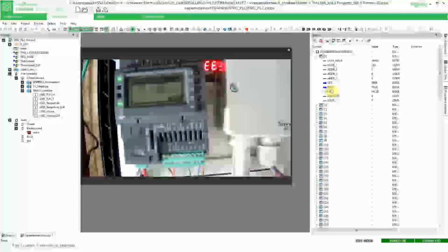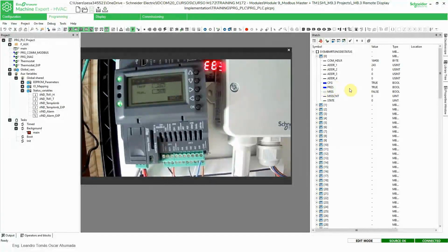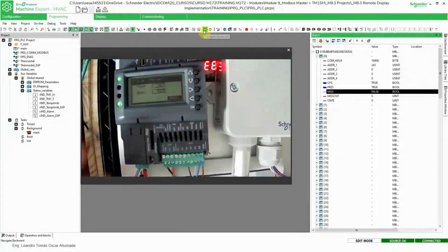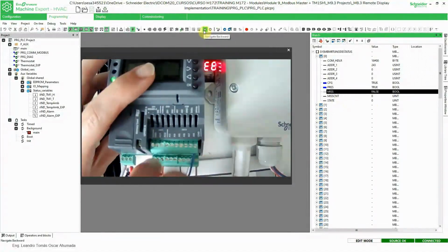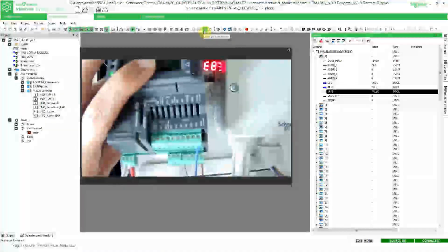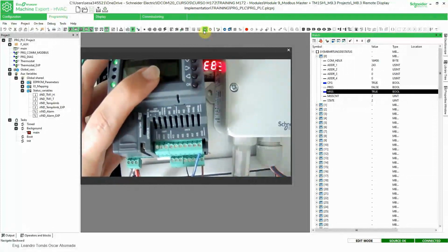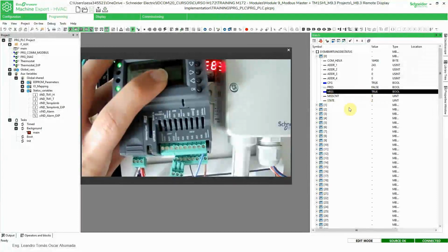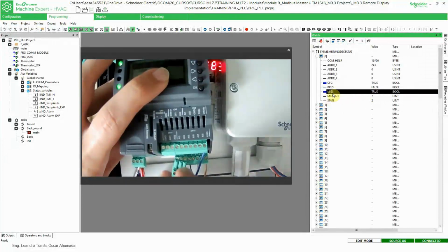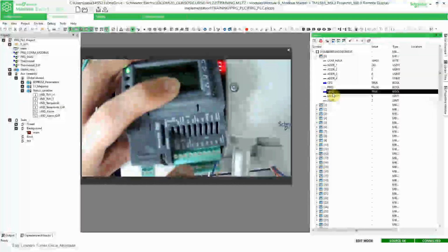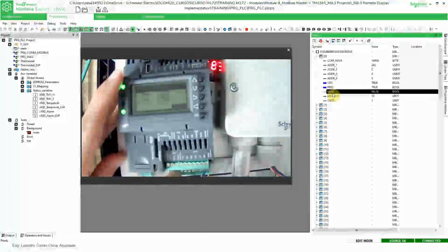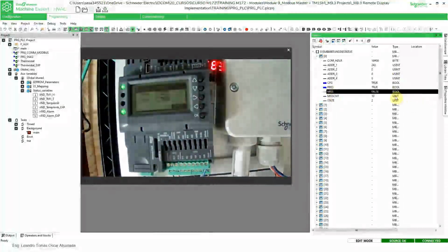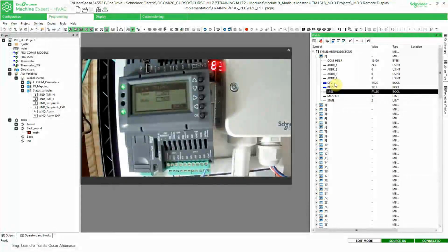So as you can see here, using the communication block. And if I remove this, we should see something here and a new state. So let me just remove the Modbus cable. There we go. As you can see there, we see the miss is true, and we have a different state in the Modbus. So if we go back, there we go. The present is true again.